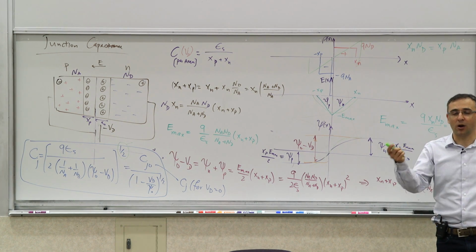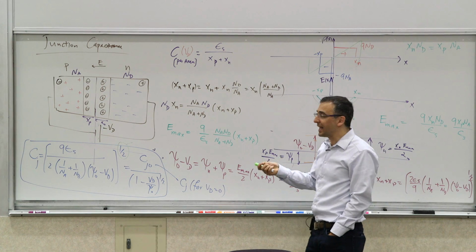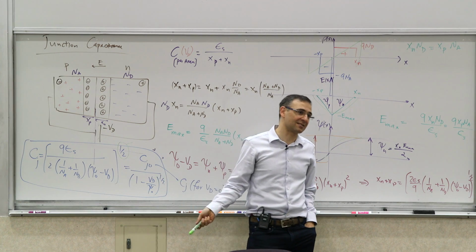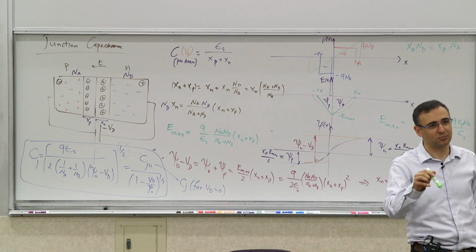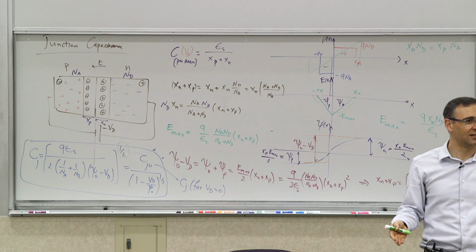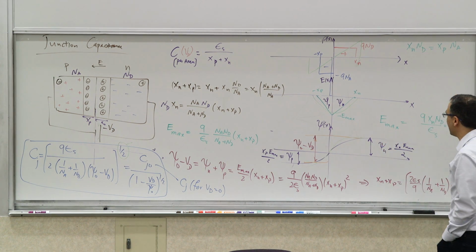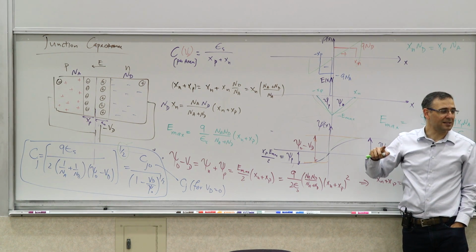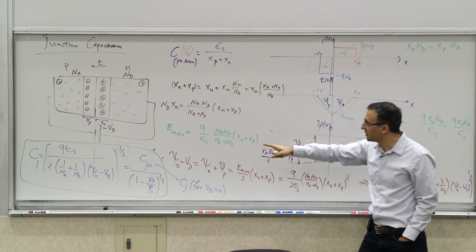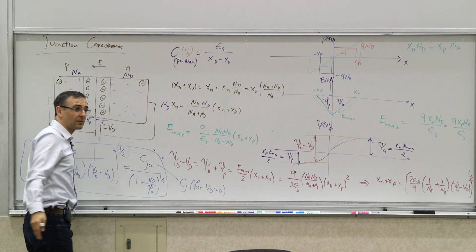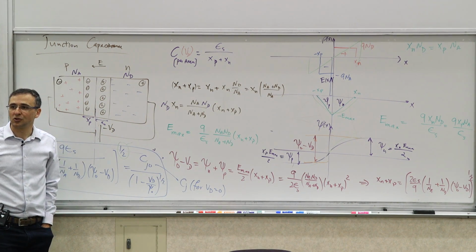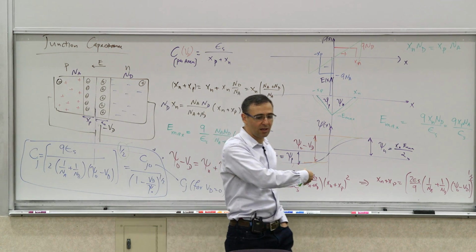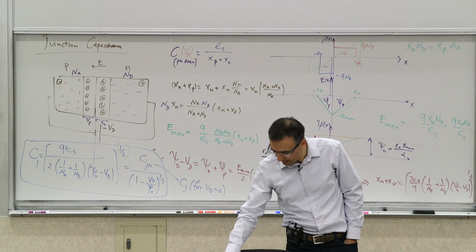So in one of your homework problems, you will deal with that. And not only that, you will also design a profile that would give the circuits designed with that varactor a certain preferential behavior. When you do that, you realize that, okay, well, these are not the only two profiles you can have. You can make a certain profile that would give you a certain exponent here that may or may not do something useful for you at that point. So that's part of the engineering part of it. You have to understand the analysis to be able to design for that.